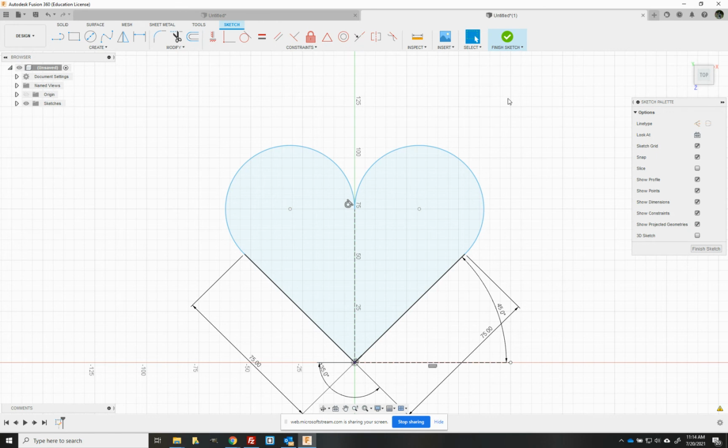The arc tool, remember, if you have your line tool, I guess I should have explained that a little better. In the line tool, if you click and drag, now I must have let it go and slip. You click your line tool, there we are, and it will create an arc.